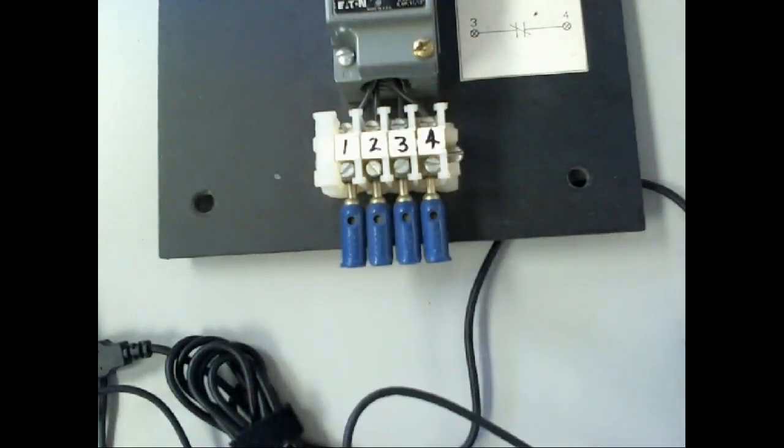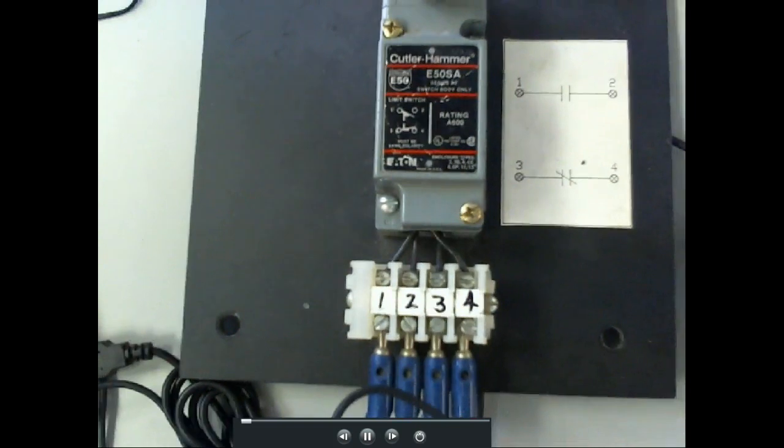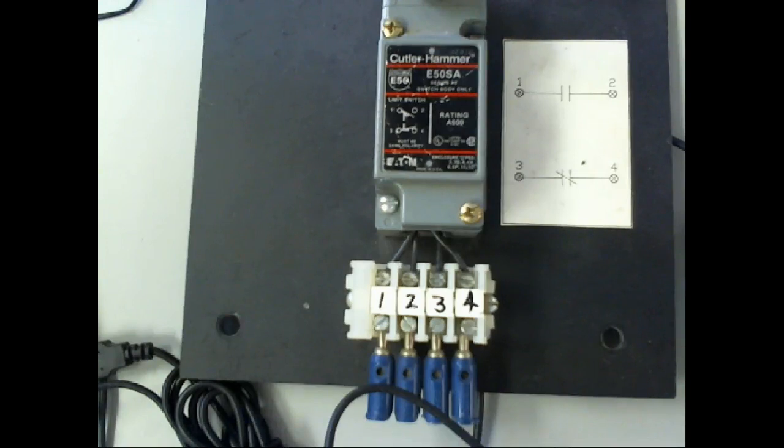Why the first push one you put fast around only had one? Well, that's what I was saying. This is a lot of industrial and that's why I wanted to show you that. A lot of them give you a design so you can just stack them on there to get whatever you need. So you could put 2 normally closed and 1 normally open. And of course, the more you get on there, the harder it is to push. Yeah, the one I had only had 2. It's going to have at least 1 down there, right? It could have 2, or it could actually have more. And you'll see that a lot in industrial because that way the company doesn't have to keep a bunch of spare parts, right?